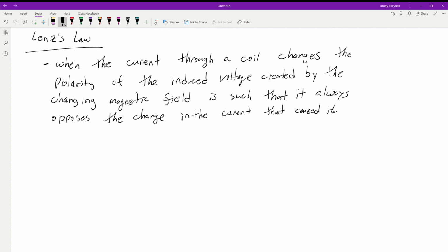So basically what that's saying is, once we have a field that's established, when it shifts polarity and the magnetic field gets built up differently, it's going to oppose the voltage that's already there for a second, and then the magnetic field will dissipate enough, and then you'll see this change. That's why when we're changing things back and forth, we have a little bit of a delay when we switch directions that we can actually measure. As soon as it switches directions, it's going to be opposing the new current, and for a split second, it's going to hesitate just a little bit before it reaches its full potential. It's not instantaneous, but we'll be able to see a little bit of delay when we shift polarity.